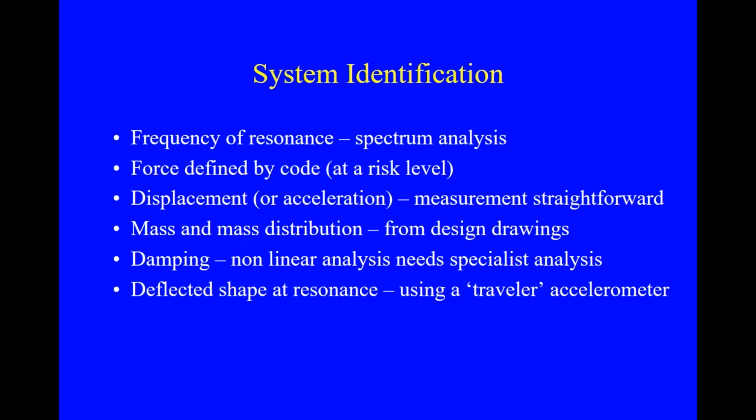And I'm going to show you, it actually starts at a low value and works its way up to a high value. If you assume that at all amplitudes of response it's the same value, you actually get the wrong response. And that can be wrong by anything up to 100%, given the right circumstances, the right sort of phasing of the force that acts on the structure. So this nonlinear characteristic of damping is really important. It makes a very big difference to the real response of a structure.